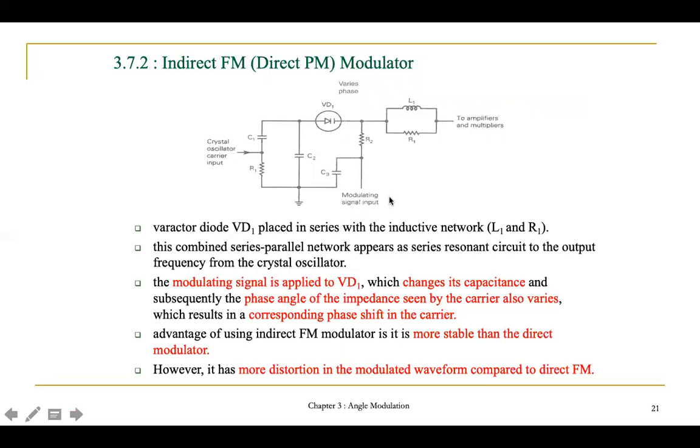The modulating signal is applied to VD1, where it changes the capacitance and subsequently changes the phase of the impedance seen by the carrier.